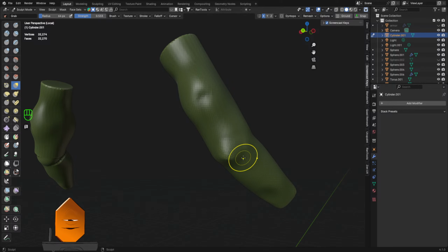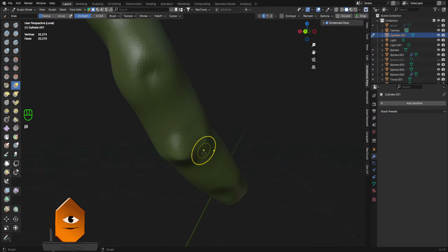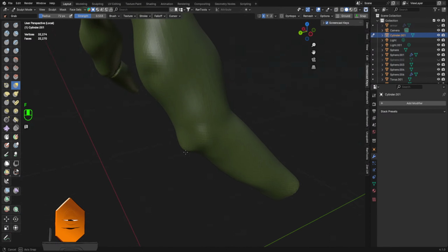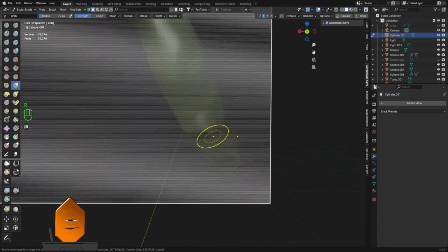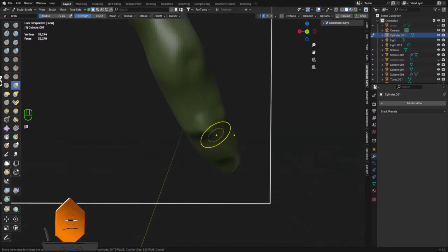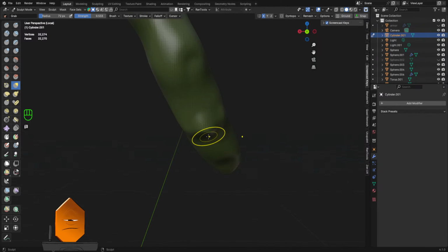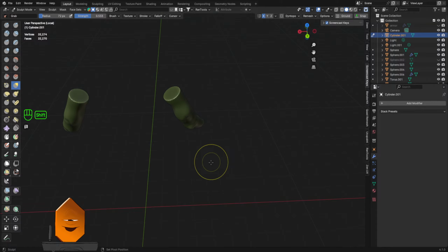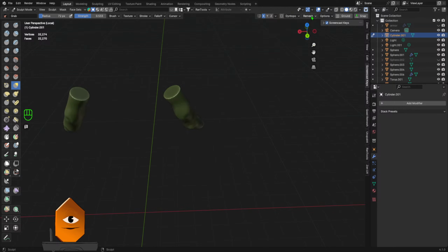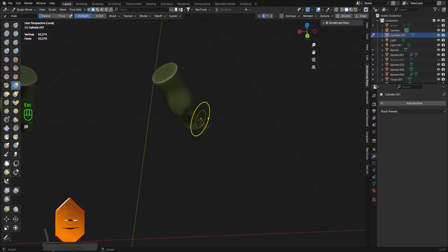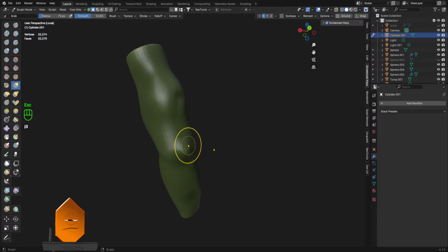The number of times I crashed Blender after meshing accidentally too high. Yup. I've been practicing sculpting a lot recently, just hitting R and using my tablet. This is actually the spot where you probably want to use your mouse, because just hitting R and using your tablet is not always very precise. So either using your mouse or going to the remesh options up here and typing in a value you know to be safe is probably better.